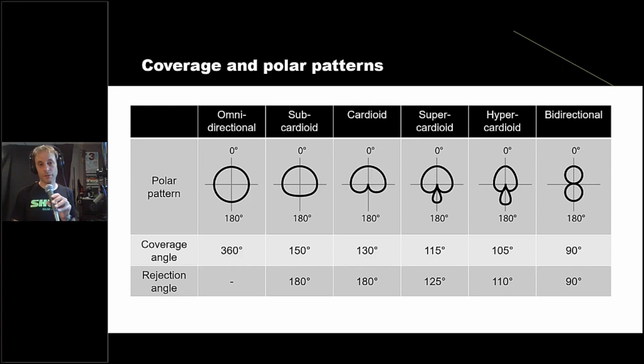Now, one thing we didn't talk about with directional mics is what's called proximity effect. And proximity effect is a boost in low frequency response that you get as you get closer to the microphone. And I'm going to demonstrate this with the supercardioid because it has even more proximity effect than a cardioid, and because it's more sensitive, I'll be able to do a gain adjustment here. Because what I want you to notice is how the low frequency response of the mic changes when I get close to it, but I have to lower the gain so you don't just hear it getting louder.